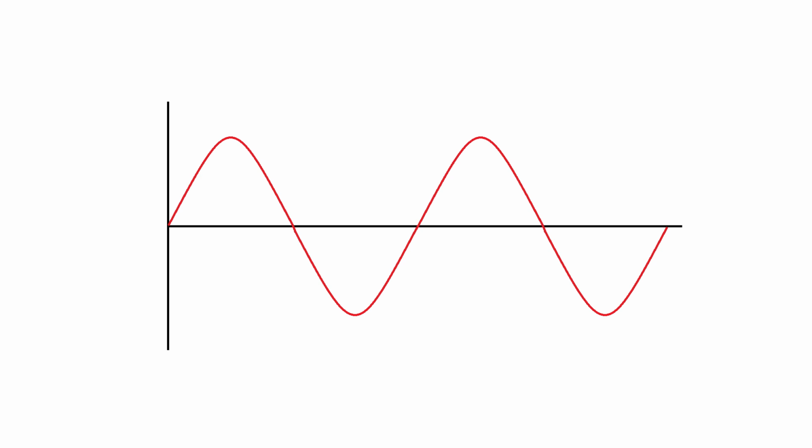And we also look at the current, and it looks kind of strange, right? Because, yes, it's still a sine wave, and it still has the same magnitude as the current in our light bulb, the same amplitude, I should say, but it's no longer in phase, right? It doesn't have the same timing as the voltage anymore.